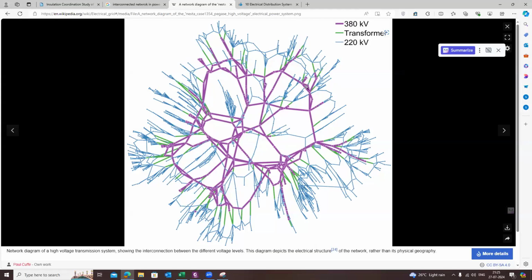So the very basic, first purpose of performing a load flow analysis is to find out the equipment loading in systems like closed rings, weak mesh, and interconnected systems, but it is not really needed for radial systems. Even if you perform a load flow analysis for a radial system, you will find the equipment loading, but that is not really needed.